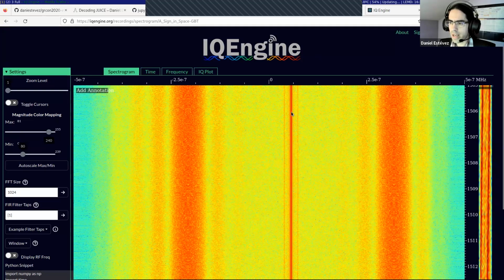This is quite similar to what Wael was describing as something which can only be artificially generated, and also very simple to detect because it is a pure sinusoidal RF waveform. And this is called the carrier of the signal, or the residual carrier.